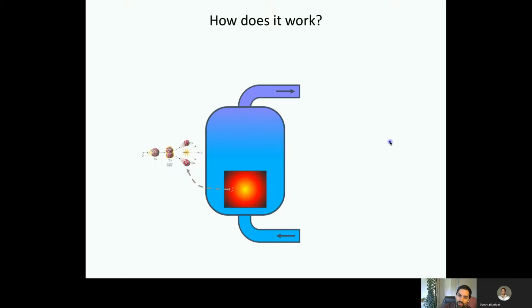So that would work, but first of all, the heat that we transfer to the water is very little because it only goes through the surface. And in the middle, the thing is going to become so hot that it's going to melt. So it's not the best way. It's better if we take that block and cut it into a lot of thin tubes like this.